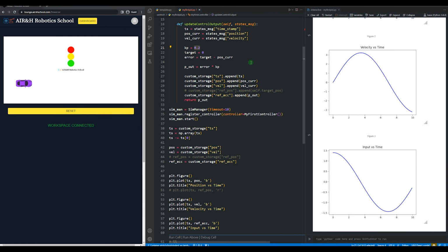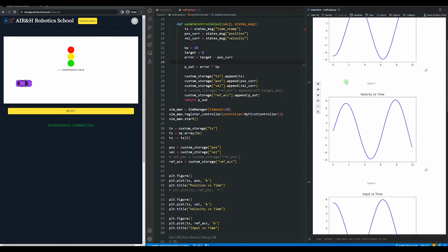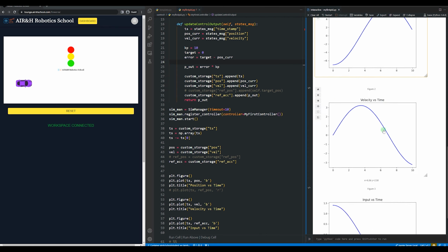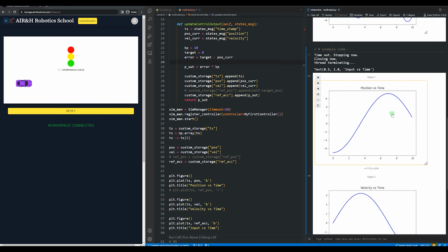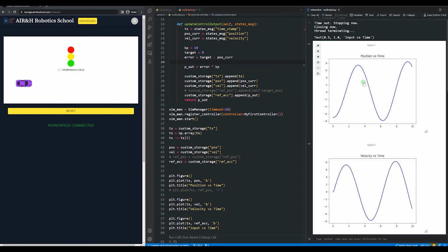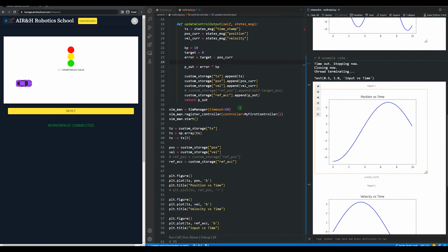And then what if the Kp is 10? Oh, by the way, currently it went up to 3, and previously when Kp was 1, it went up to 8. And then when Kp was 0.02, it was 6. And the velocity went up to 3. So my point is that the amplitude is kind of lowering down, and then the period was extended. If we compare to this, we had this 1.5 period, if it's a sine or cosine graph. But now the period was extended here with the lower Kp.